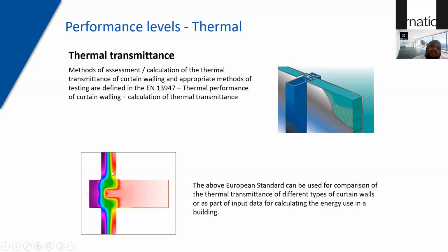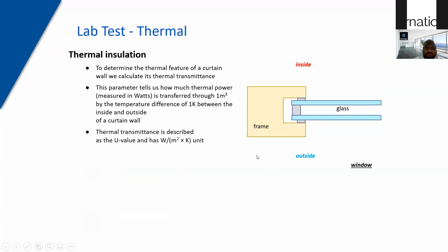When you have heat transferring from outside to inside, your boundaries, your frames, are basically having thermal bridges. So it is not enough to have a great glass, because if you use poor framing, it's like having a wonderful dam with leaky edges. All the heat is going to transfer through your edges.